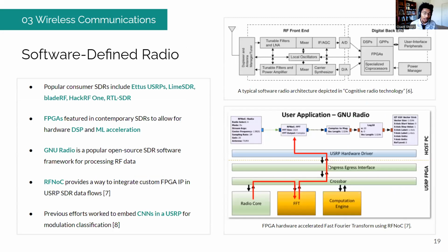And so that's kind of an overview of what the spectrum sensing problem is. How this can actually be tested and evaluated is using devices like software-defined radios, which is what we explore a little bit in this study. So software-defined radios are essentially devices that we can use to manipulate and control data that's being transmitted over RF spectrum. Essentially how it's made up is shown on the top right here. So there's a combination of an RF front end and a general purpose computing area.